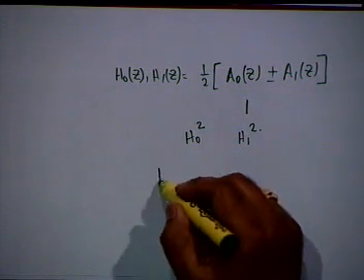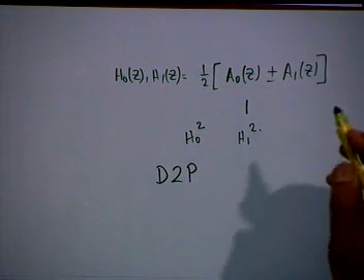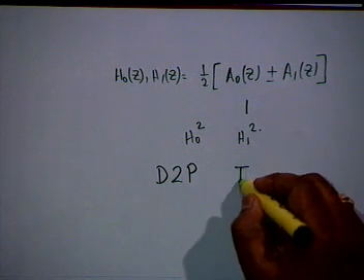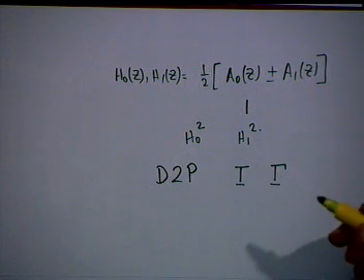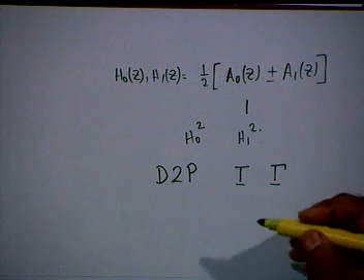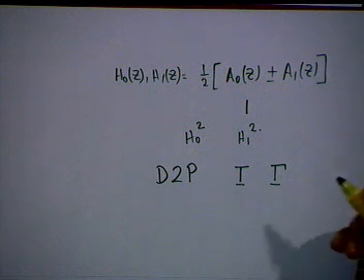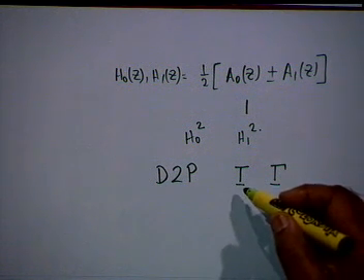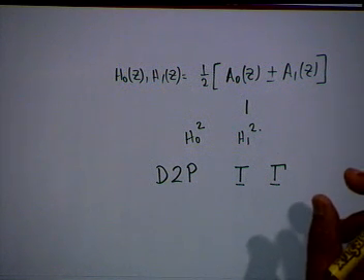Then we introduced the concept of digital two pairs, and we showed how they can be represented by a transmission matrix and a chain matrix gamma, and we showed how cascades can be of two different types, transmission cascade and chain cascade, in which the respective parameters multiply each other to get the overall transmission or chain parameters.